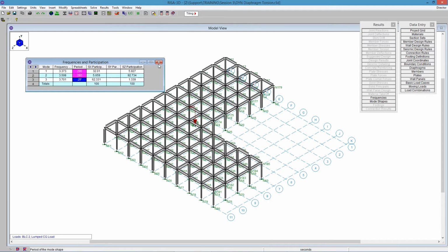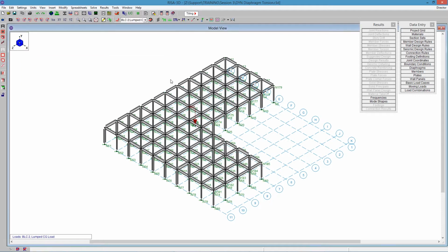In this structure, it really doesn't make much of a difference how we chose to do this, but what I wanted to do is demonstrate the different ways you can do it, and then you can do it on your own in your model. Depending on the type of model you're looking at, you may need to do it different ways. I would say the first approach is always to use the easiest, so just use your loads based on your seismic load. And then if you have to go to a mass, you can walk down that path as you need. Let's jump back here.